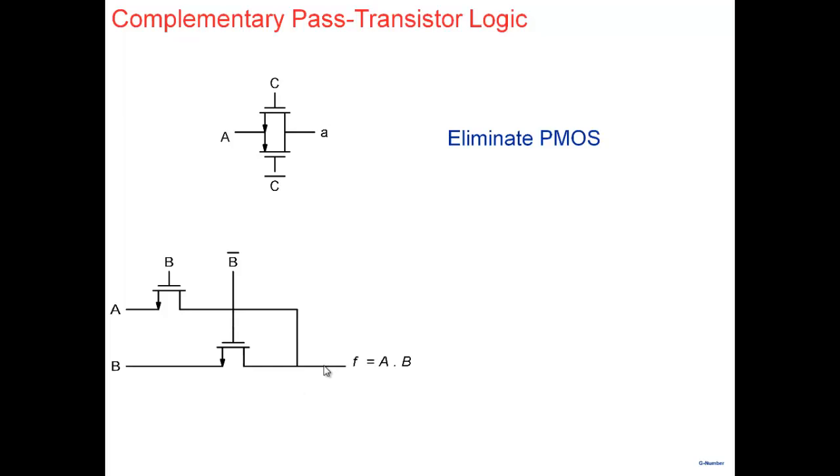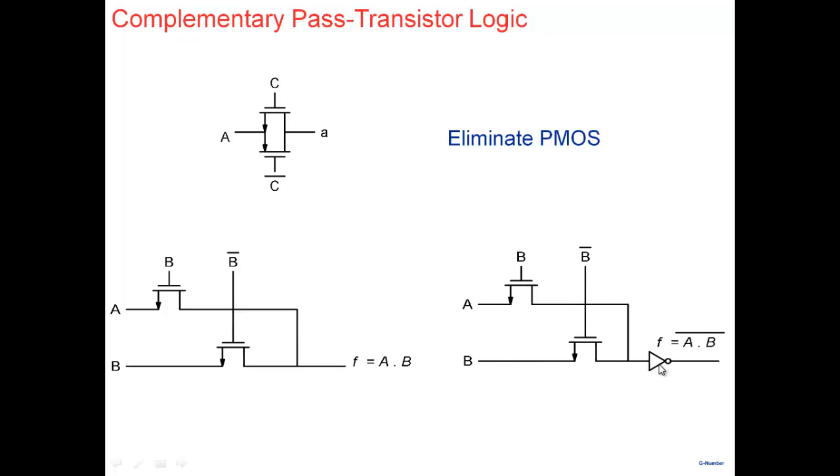So now what I do is, maybe I add an inverter. Even though I may get a poor one, the inverter will sort of restore the logic. It may be a poor one, but then I'll get a proper 0, a strong 0. And it passes a proper 0 here, so I will get a strong 1 here. So the inverter is being added to restore the logic back to strong 1 and strong 0. So that's the idea: use an NMOS here, and with these NMOSs add an inverter to restore the logic back to strong 1 and strong 0. But it's not as simple as that.